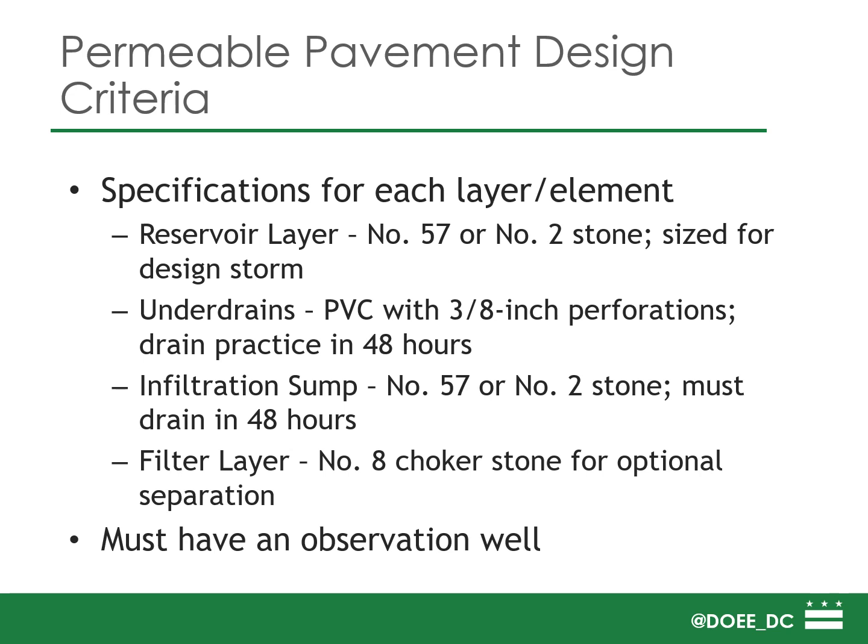The filter layer between the subgrade and the reservoir layer is typically number 8 choker stone. And as I mentioned before, all permeable pavement systems have to have at least one observation well.